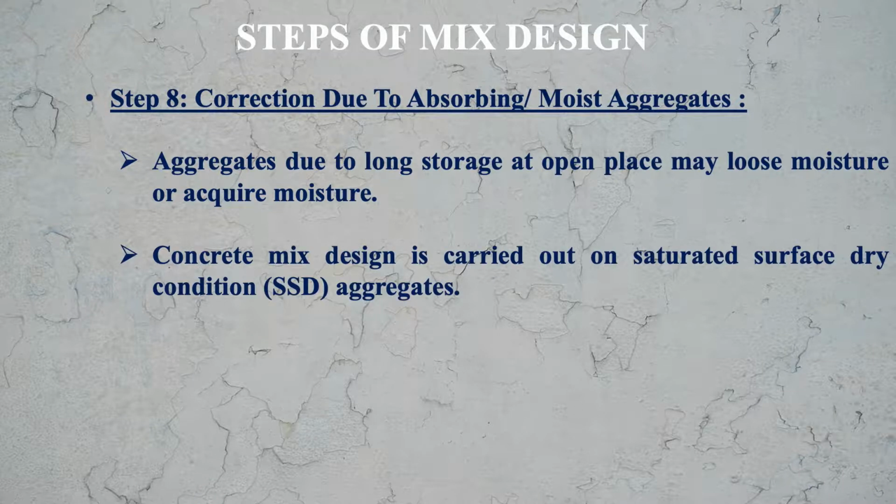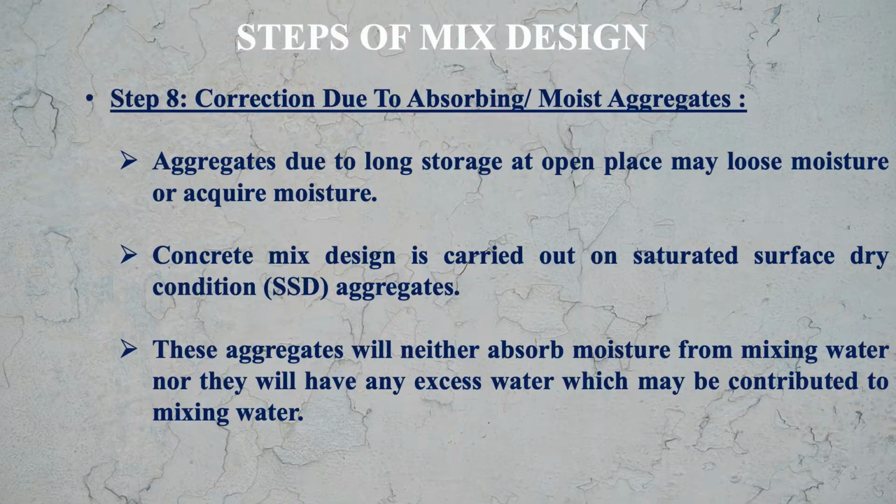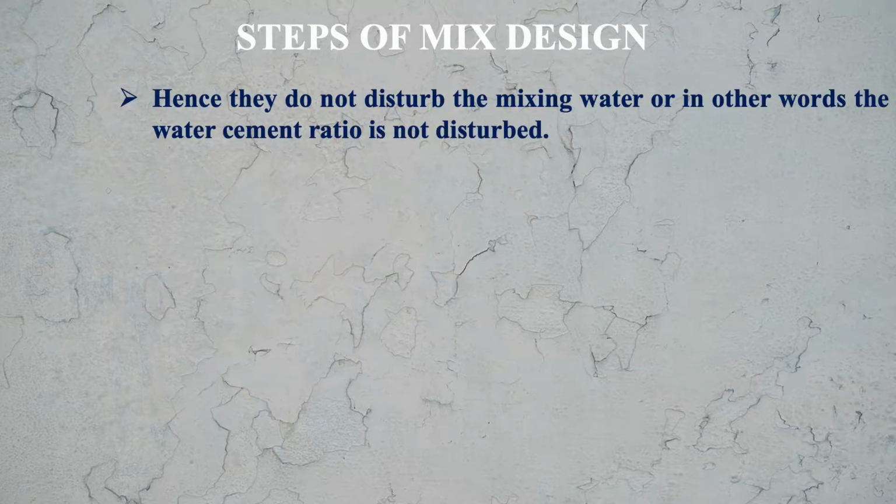So concrete mix design is carried out on saturated surface dry condition aggregates, that is SSD aggregates. Means we are assuming that we are using the SSD aggregate. So with that assumption we are doing the concrete mix design. These aggregates will neither absorb moisture from mixing water nor will they have any excess if we are having the SSD aggregate. Hence, they do not disturb the mixing water, or in other words, the water cement ratio is not disturbed if we are using SSD aggregate.